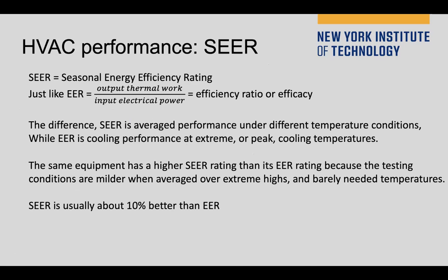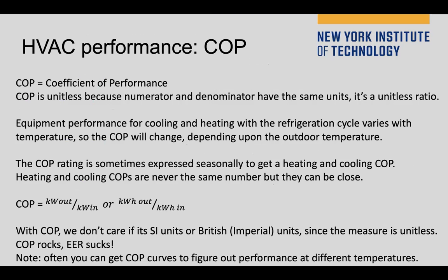I would like to show you one more slide about COP. COP is the coefficient of performance. Again, the difference between COP and EER is the unit. They represent the same thing, the output thermal power over the electrical input power, but the unit is different.